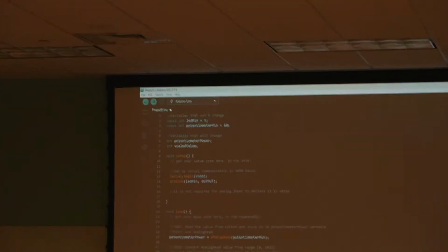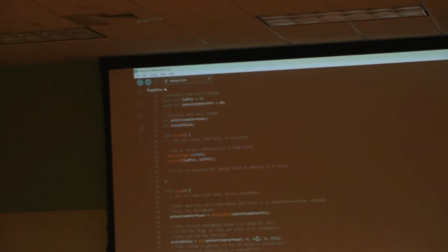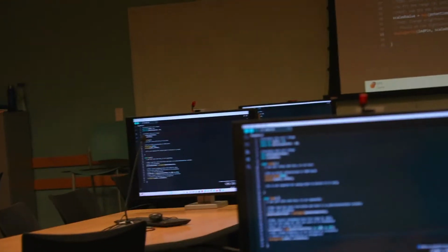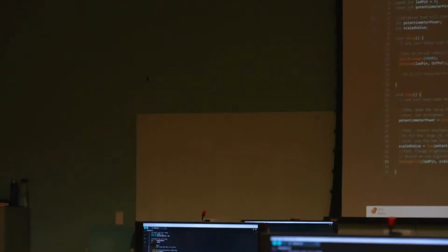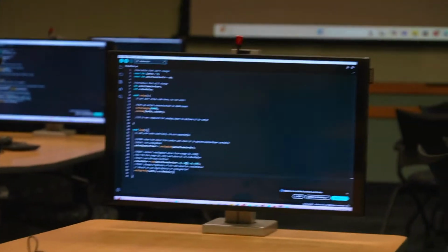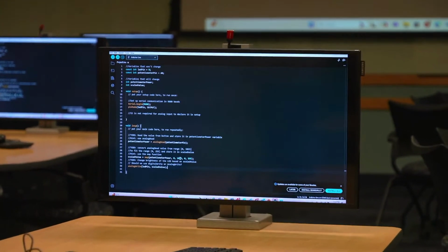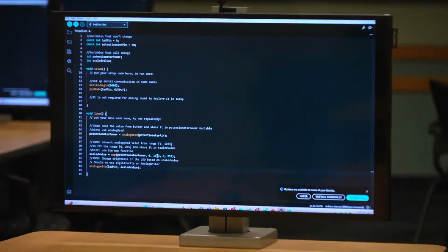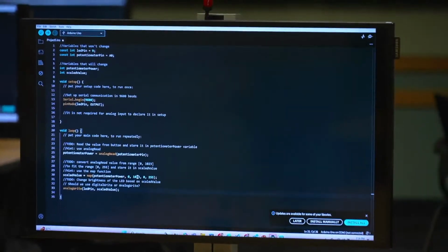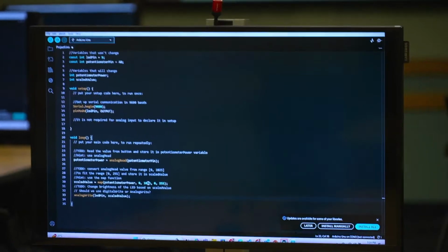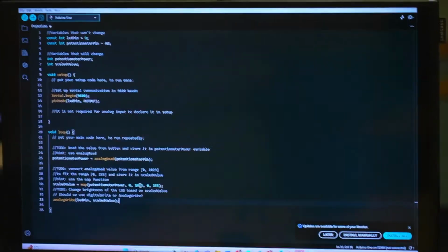Did you try to debug it, to see the analog values? Hold on. Oh wait, let me see, because maybe you're missing something. Oh, you know why? Because you're putting one pin here on the other side. So after we send the code in, it's supposed to turn on, right? The LED. The upload, yeah. It's not turning on.